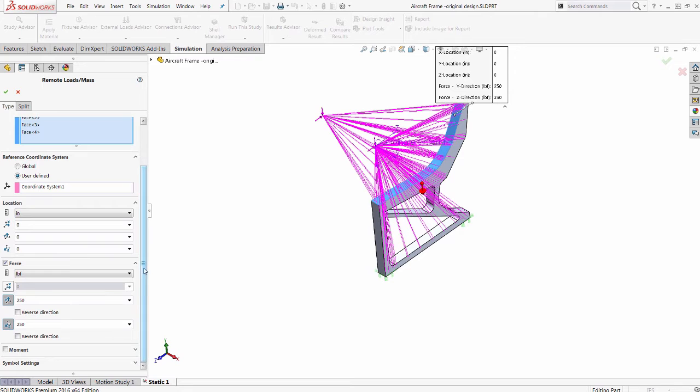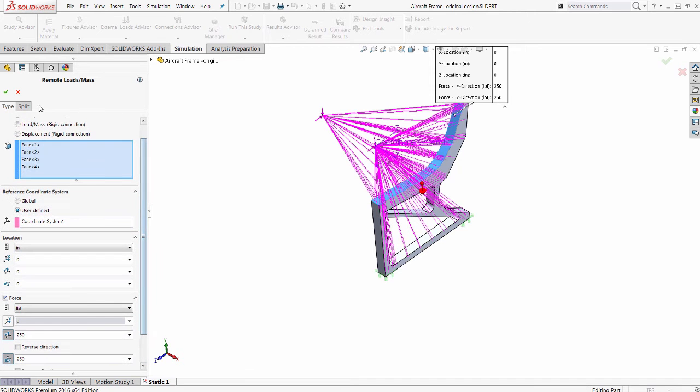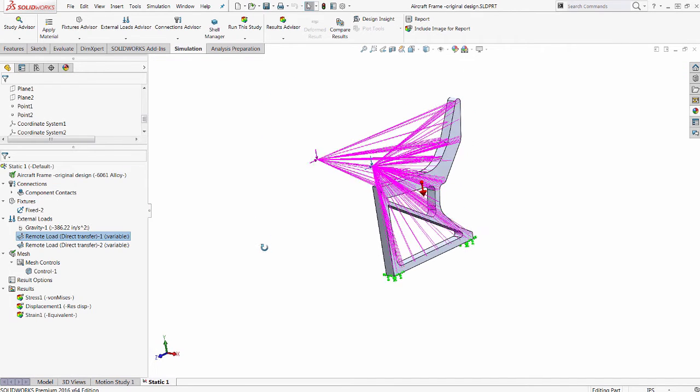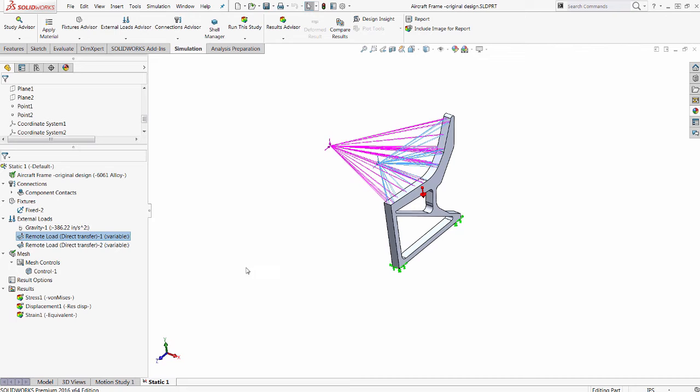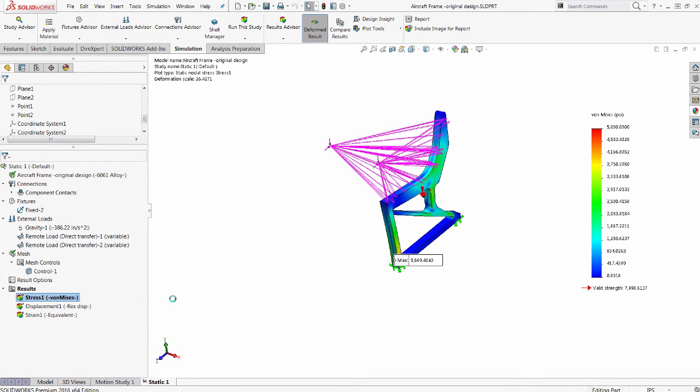So that's the location of two people sitting, and I took a maximum weight of about 350 pounds and found different components of it. So yeah, having said that, here are the loads, and looking at some quick results, we see that this initial configuration has a factor of safety of about 1.6, which is not too high because we're still looking at only a static analysis.